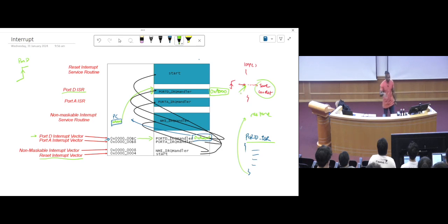Okay, so this concept of interrupt processing is uniform. That means across all controllers, they have the same idea. I have a vector table which basically tells me where I will go when the event happens, but in the vector table, I only have the address of where the code is stored. So I will first go to the vector table, take this information, then put it into my program counter and then execute the code.